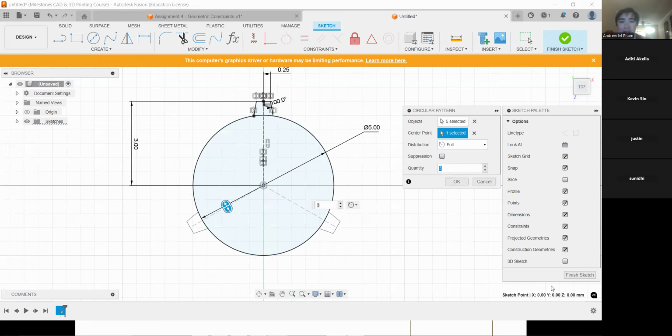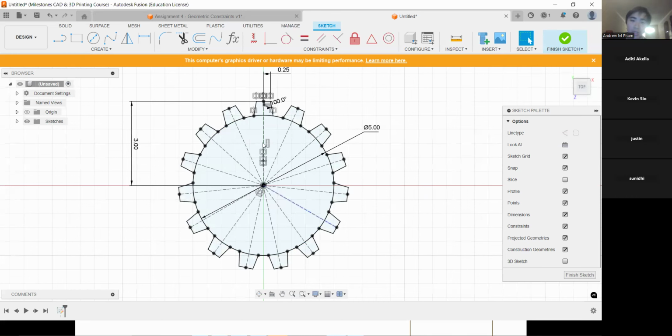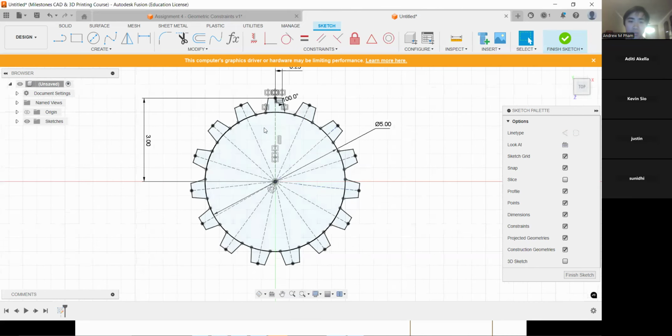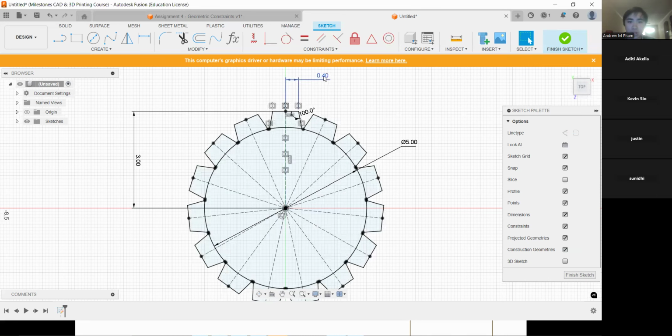And then I'll start adding teeth. So if I type 10, you can see it previews as more. It probably can even go higher. So add however many teeth you want, and then when you're satisfied, you just press OK. And now you see we have a bunch of teeth and it's looking a lot more like a gear. Again, because we copied the feature from this original tooth profile, if we change anything, it all changes with it.